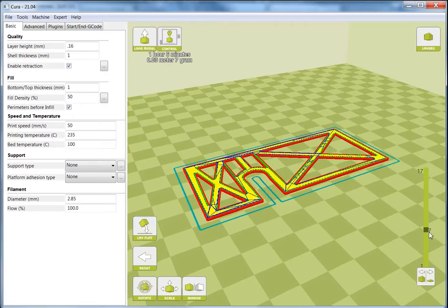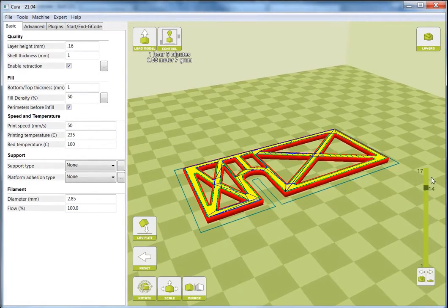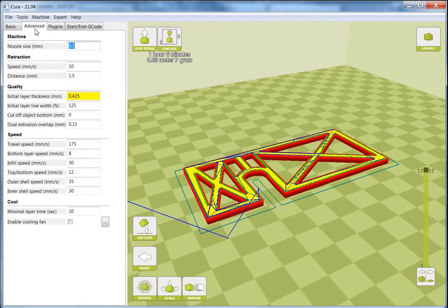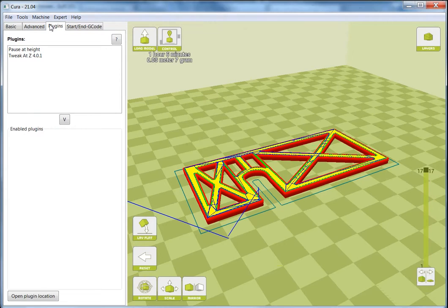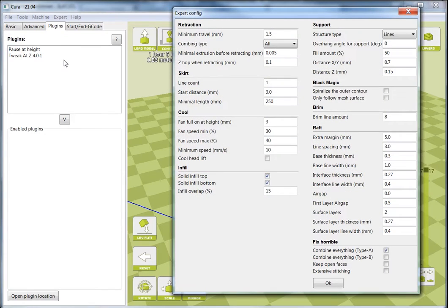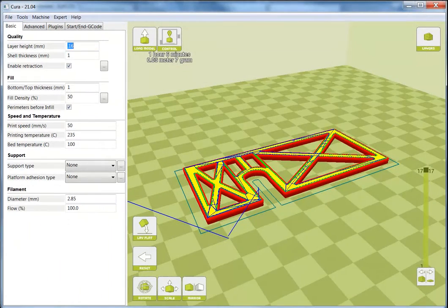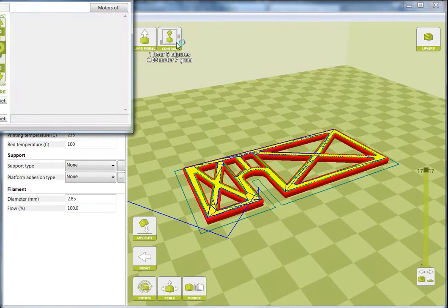and make sure that everything joins up. In terms of the controls, it also controls the heat of the head and the table of the machine, the millimeters of thicknesses for various elevation and wall thicknesses, also the speed of the printer. There's also a term called retraction, which is when your printer head has to skip from one place to another, the head actually draws the filament back up for a microsecond and then puts it down again. So there are lots of variables that you can set with the Cura program,